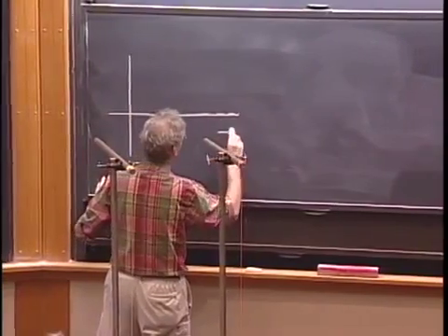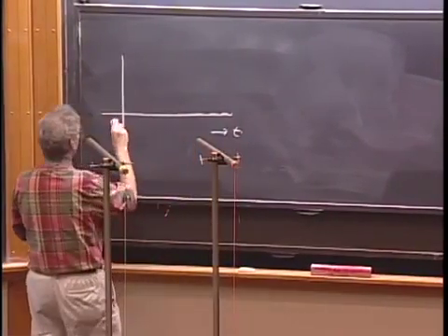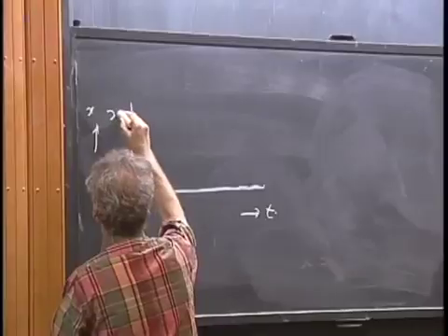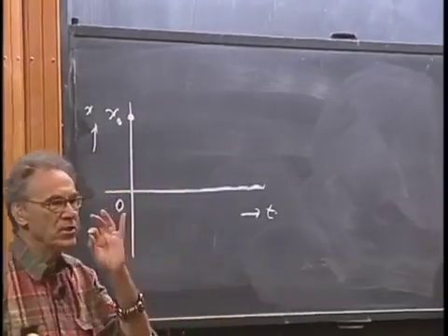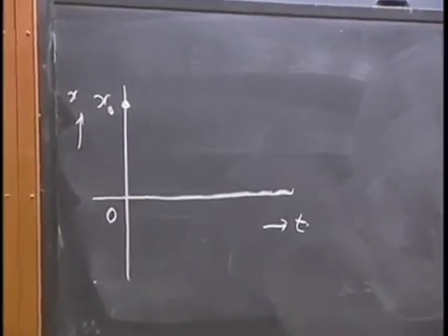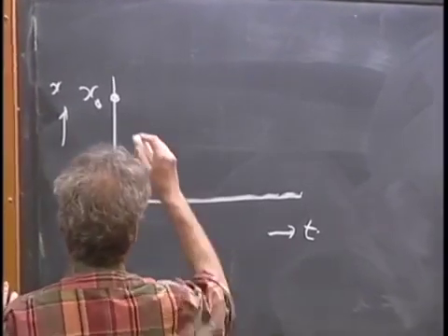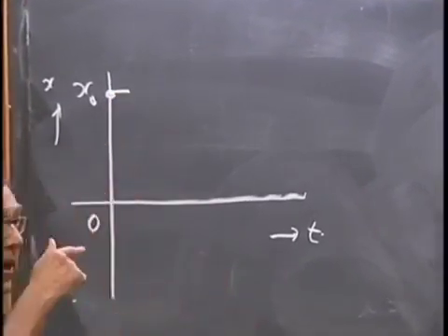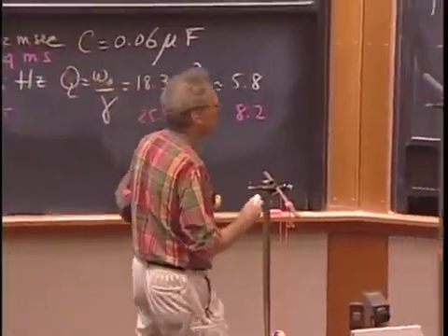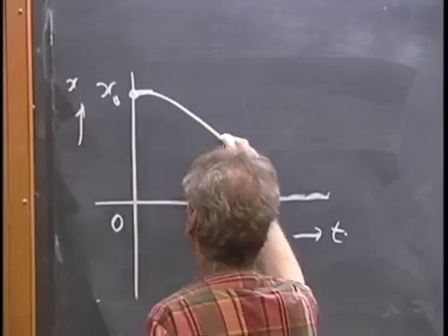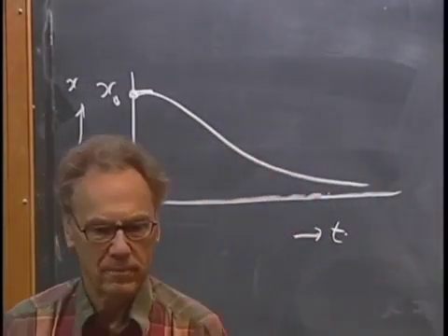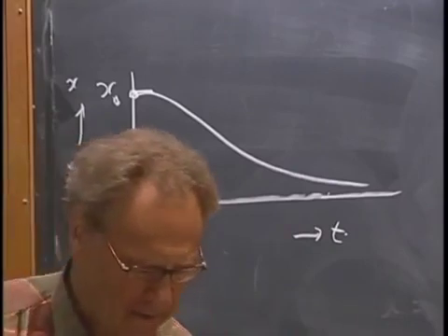Let this be a spring system, and this is x equals 0. And I offset the spring to a position x0, and I let it go with 0 speed. That's my initial condition, 0 speed. So that means when I let it go, it must go in this direction, right, in that diagram, because the x dot must be 0. But there is no oscillation, so what will happen is this. And it will asymptotically go to 0 with two different decay times.